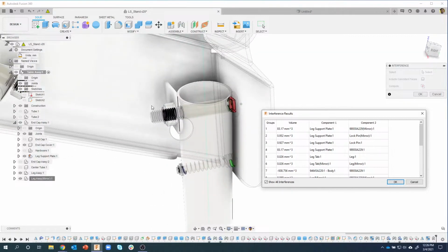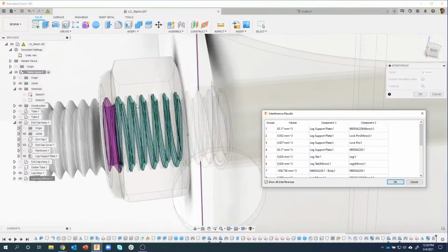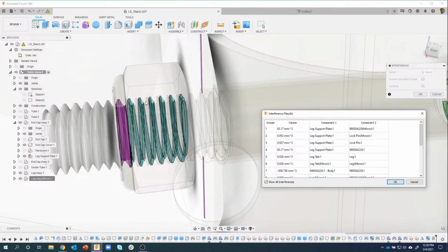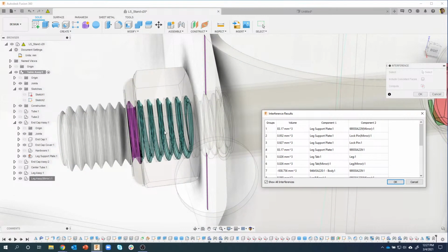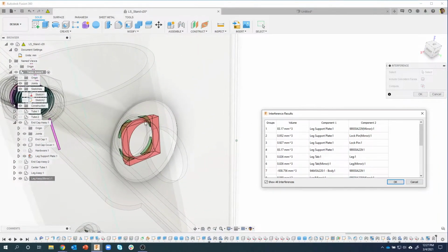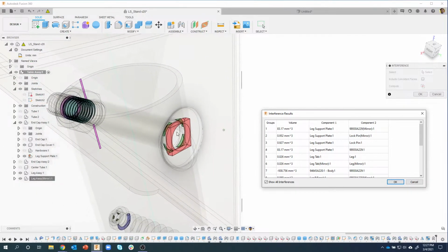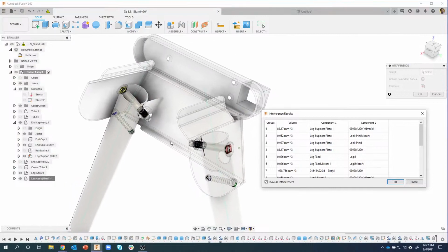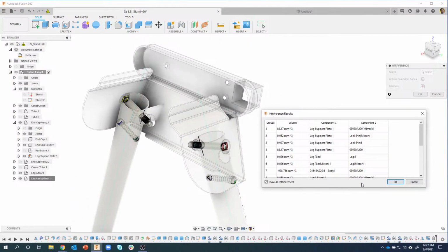And I do that. In fact, with threads, you can pretty much ignore it, because it's really tough to get, like, I could rotate the nut so it's actually binding with the threads the correct way and all that kind of stuff. But this is exactly why I think people are asking the question: I have a round hole and we're putting a larger square head through that. You guys are kind of thinking ahead. I think you know me now. This is, I'll be honest, how I design. I'm assembling this thing together, it's looking great, and I will run a clash analysis or an interference analysis after a while and see what's clashing.